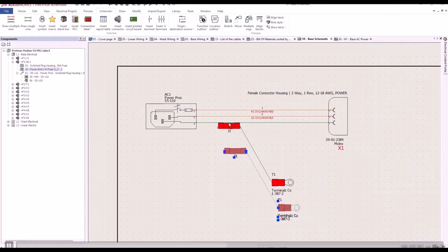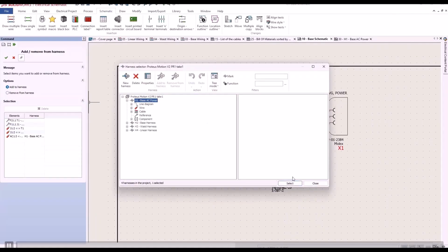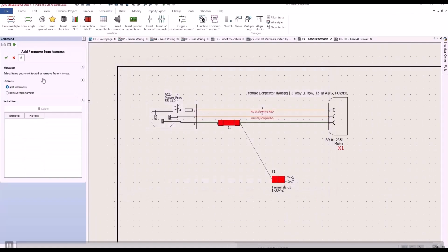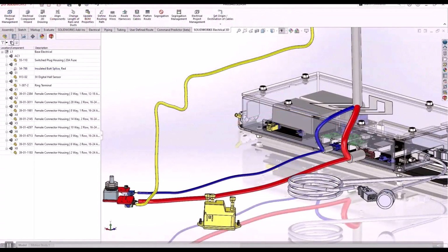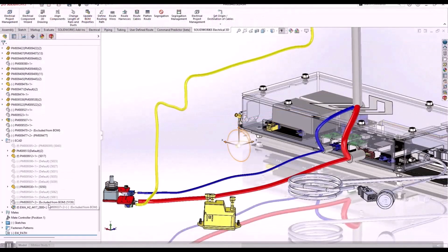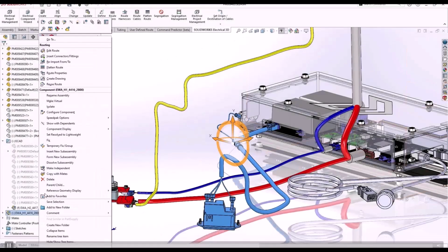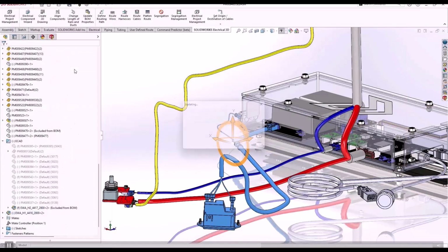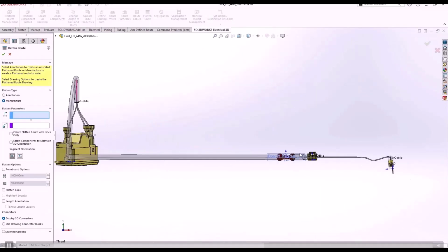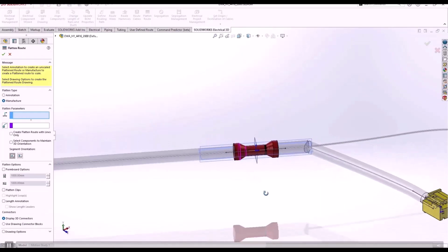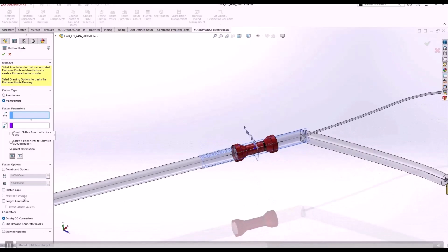Let's take a look now at some enhancements and improvements in the harnessing realm. So here we are going to introduce a splice into the circuit, handle the rerouting, and demonstrate that the flattening now produces accurate results without the loop issue. Finalizing that route, we get a nice clean assembly. Opening that for flattening and detailing now comes with some additional enhancements. Focusing in on that splice, we see no loop message reported anymore.